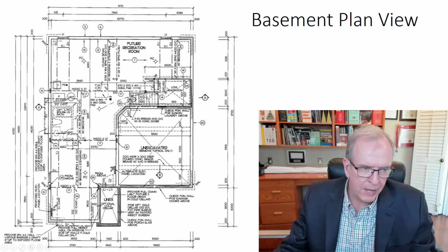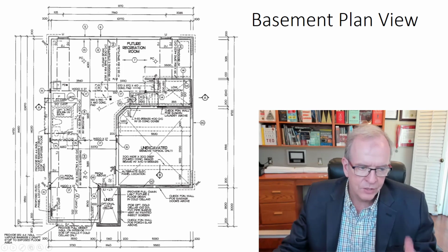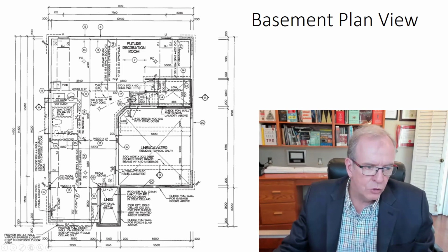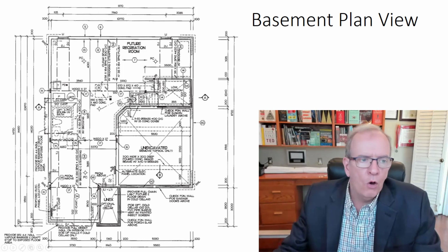So here, because of the span, they kept them at 12 inches on center. Here, they go to 16 inches on center. 400 is the same as 16 inches on center, spacing wise anyway. So we've got 2x8 spruce number 2 here at 400. This is very interesting because it's kind of unusual here: 2 38s by 184, so they're doubled here. That's because this span is even a little bit wider than this one, and they would have had to go to 2x10s if they had stuck with this. So they went with double 2x8s just to keep it the same size all the way through.